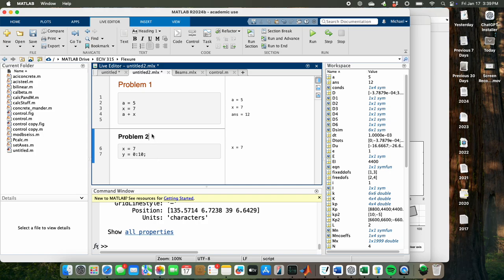There's other ways to do it in a live script. This is the live script that I'm doing. The % is the easiest way to do it, but I think that there's probably a section break right here. Yep, section break did it. And then you can put a title. You can put titles and stuff like that in there. And like I said, you can even bring in PDFs and put them in there as well in the live script.